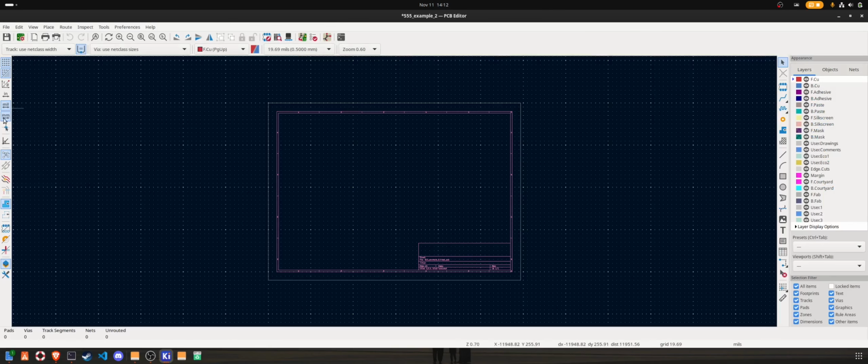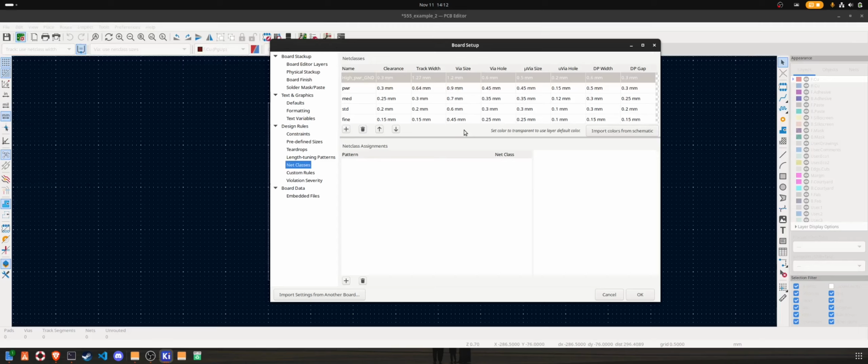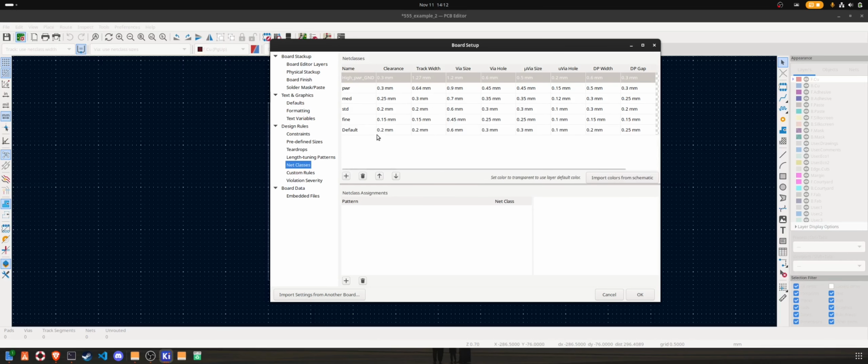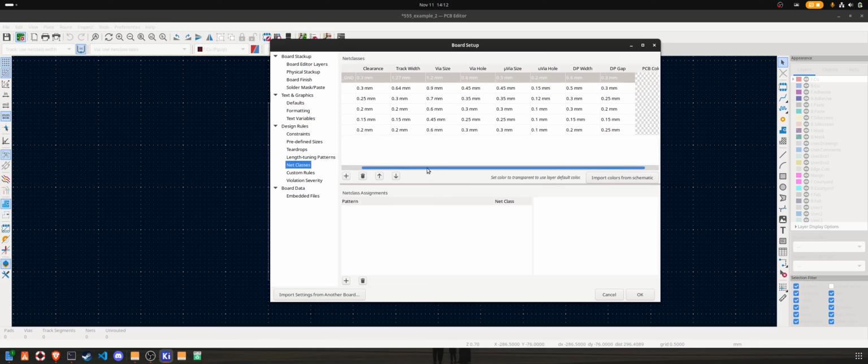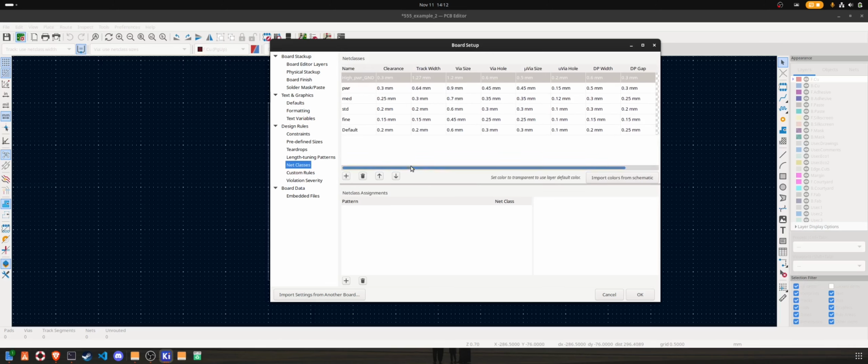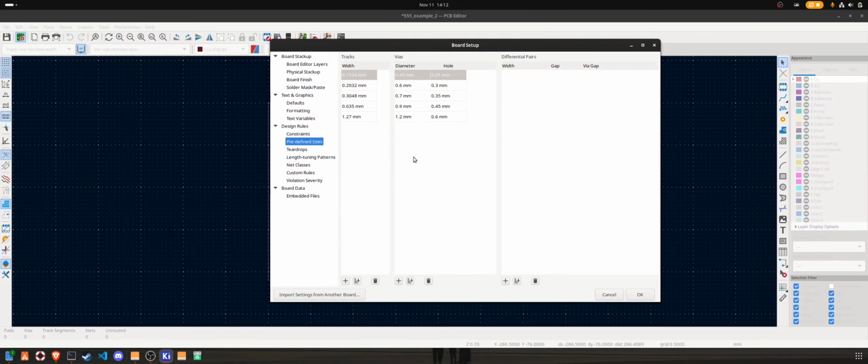I'm going to switch units so that it's a bit easier to enter them for the vias. So net classes I defined in millimeters too. So set all these up, pause it now. There's your via sizes in millimeters. And make sure you do them in order because the vias correlate to the track widths.